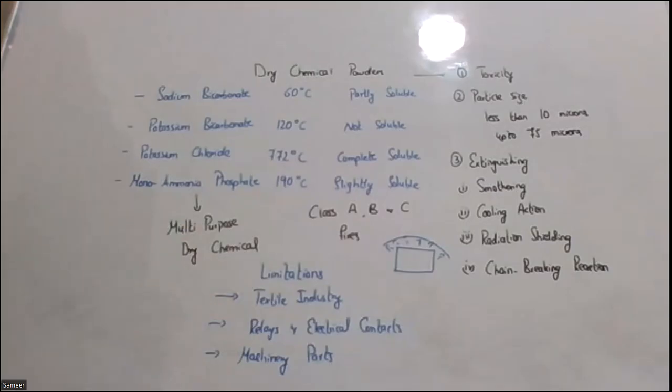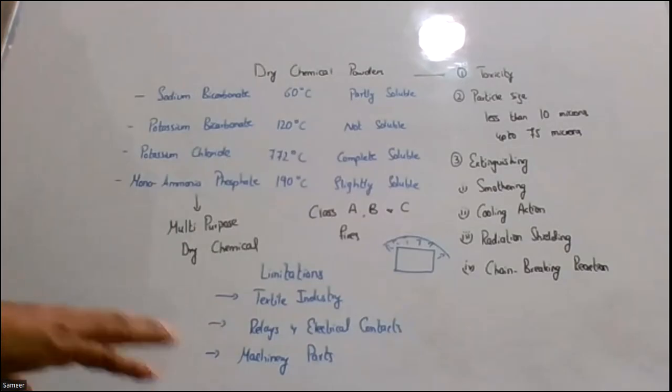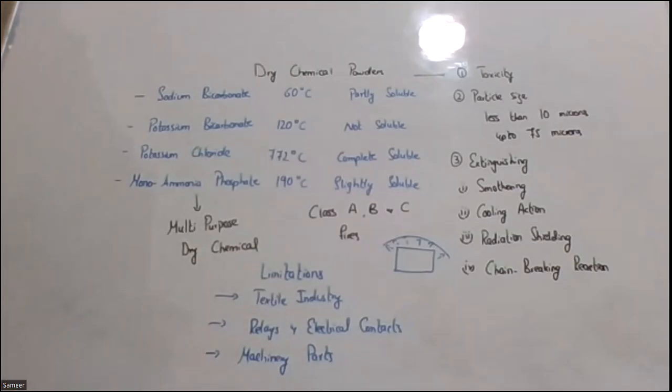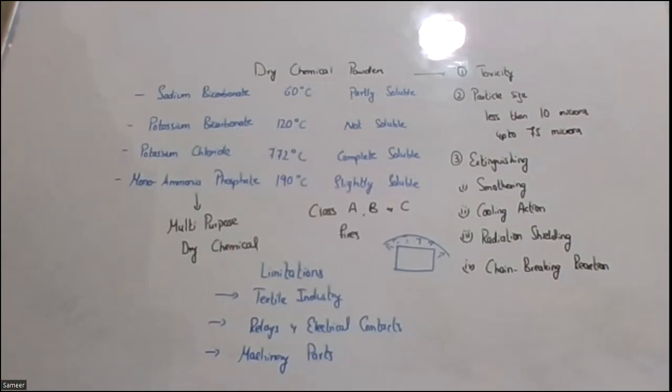After extinguishment of fire, I need to clean the dry chemical from there. When I want to clean the dry chemical powder, it has heated up and become sticky in nature, so it is very difficult for us to remove it. When we remove it by scratching, the insulation of the machinery will also get damaged. And there are some complicated parts where the powder will go, which will be very difficult for us to clean. So that is why they have the limitation, and majorly the limitations of the dry chemical powders are all because of the residue that it tends to leave over.